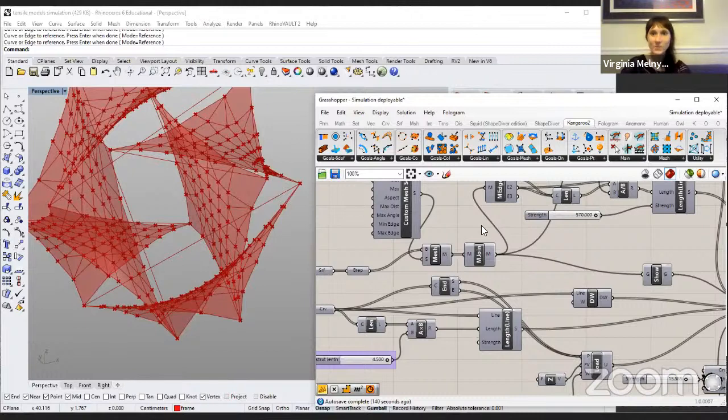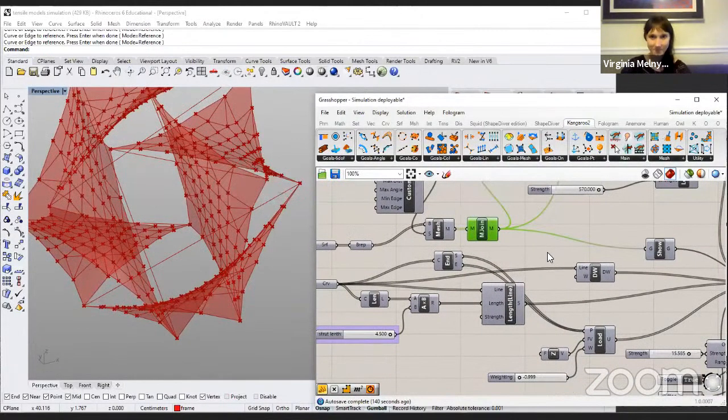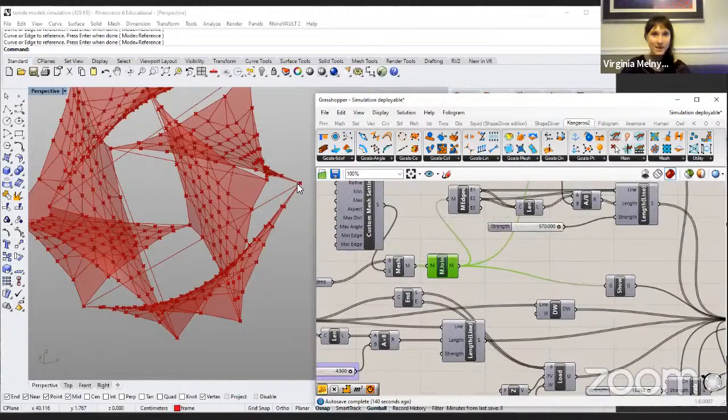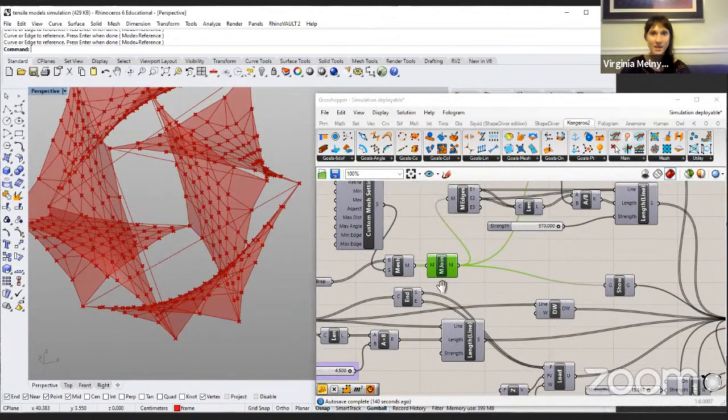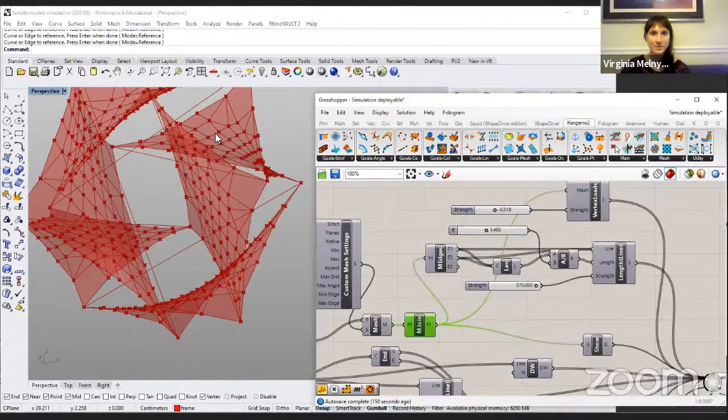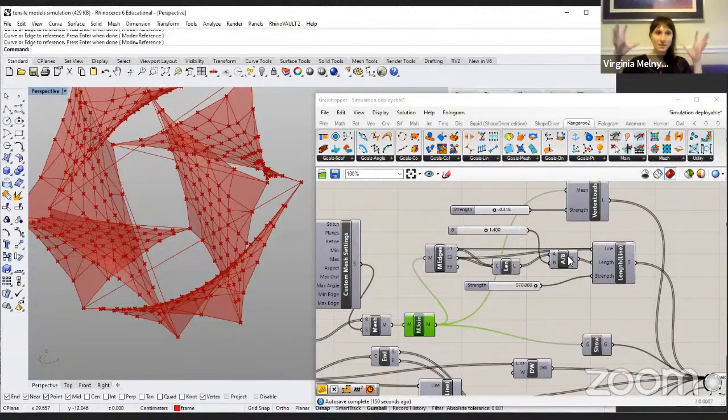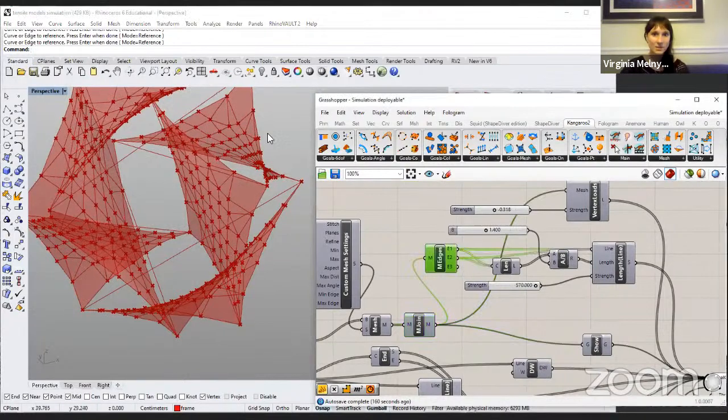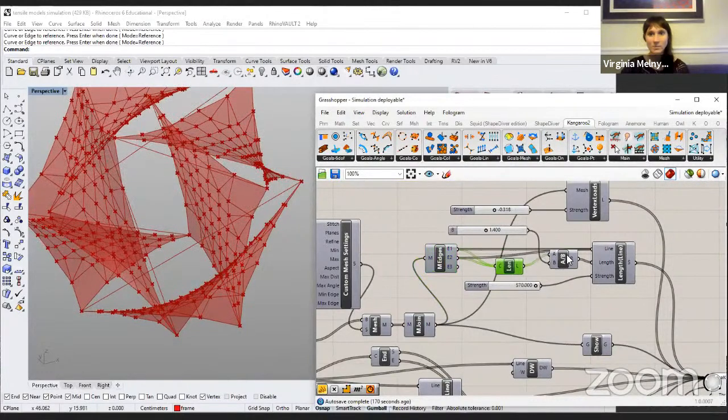Okay. Well, so mesh joins all the meshes, so that way the corners are connected. And then we can take all of the edges of this mesh, and that's when we apply the forces and the relaxation. So we make them into springs so that the fabric responds the way that a tensile fabric would and kind of shrinks. And so we do this by taking all of the edges of the meshes that we created, and we get the length of them and multiply it or divide it by a number.